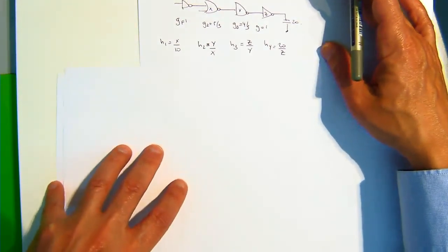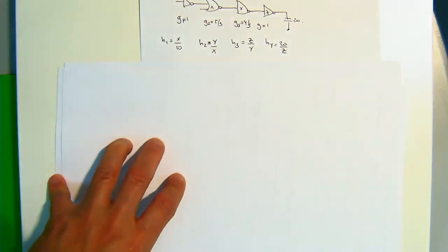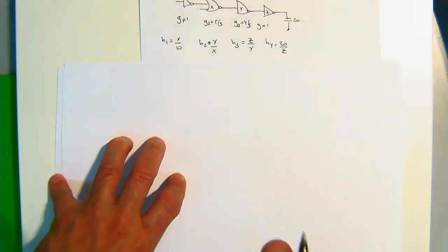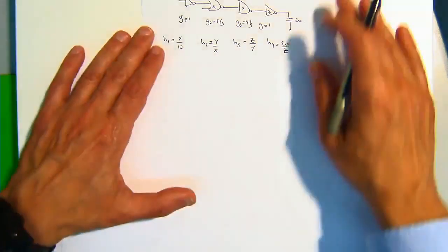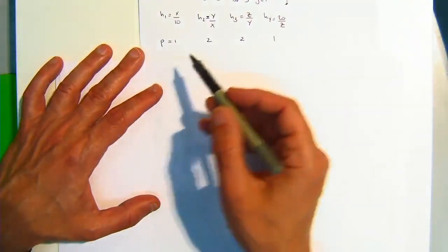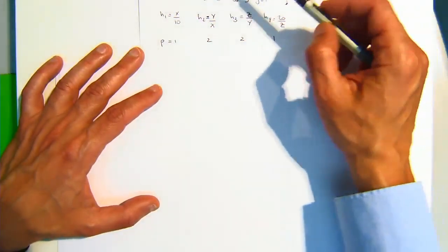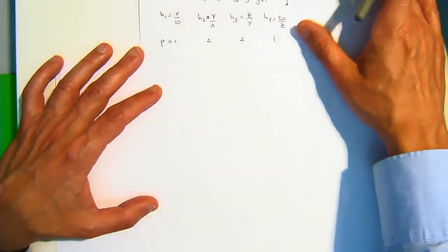What's the parasitic delay of each of these elements? All you're supposed to be doing is looking at the table, right? Unfortunately, I've given you the lecture notes, so now you're just reading them. But the problem is, by doing that, I don't know that you know how to go back and look at the table. I assume you do, but it's okay. So we look at the table and the parasitic delays, and we see that inverters are 1 and the NOR and NAND are 2.